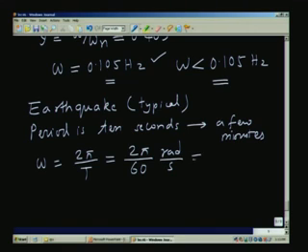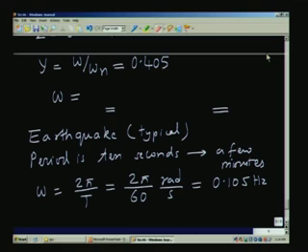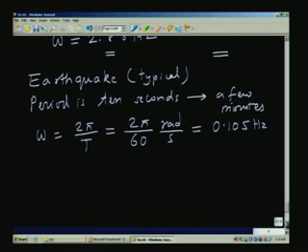and that comes to about 0.105 hertz. I think the above result was not correct. I will correct this. This comes to about 2.86 hertz. And you see here that if you have 1 minute as the period of the earthquake generated wave, you get a fairly low input frequency, and the accelerometer will certainly respond to this very well.